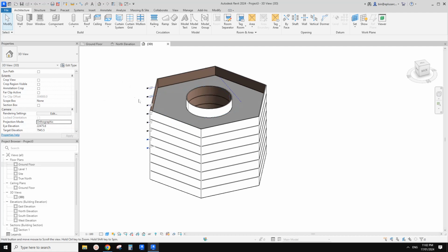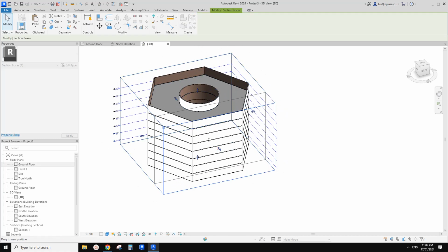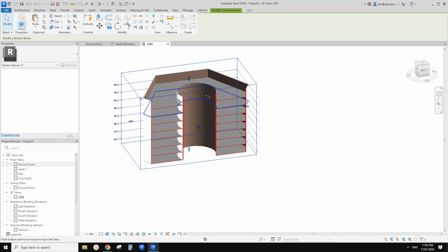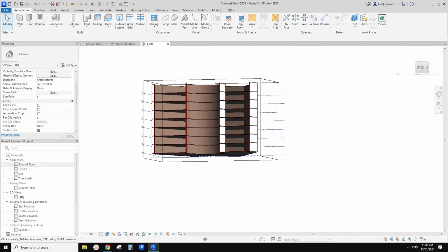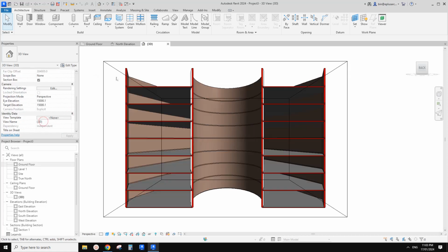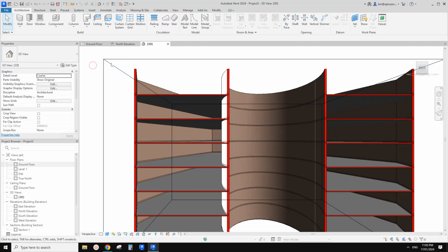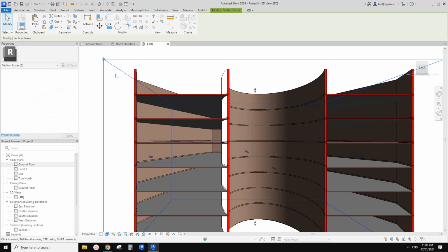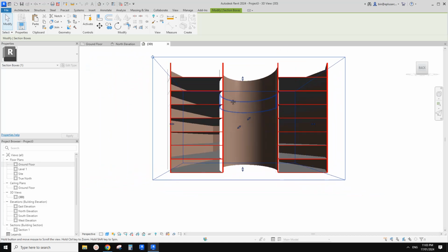But before that, let's just tick the section box, okay, and then we can just cut this back, and then you can manually do this roughly, or you can just click on this, right, and then tick change that to perspective. Okay, so then that's it. So now this usually section box, when you export or print, it won't show on your drawing, on your PDF. Yeah. So you can see it.